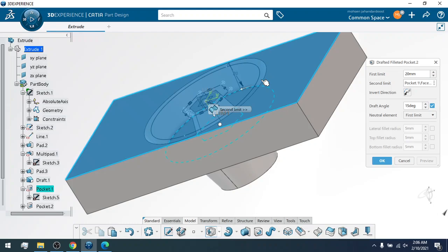In manufacturing, this is the correct design, because when you make it in the mold or injection molding, this is the way that you have a positive angle and it can come off from your mold. But if you create, for example, let's say that this is your plastic, but if you have negative values, then your product gets stuck inside your mold and you cannot take it out after you create the product inside the injection molding.